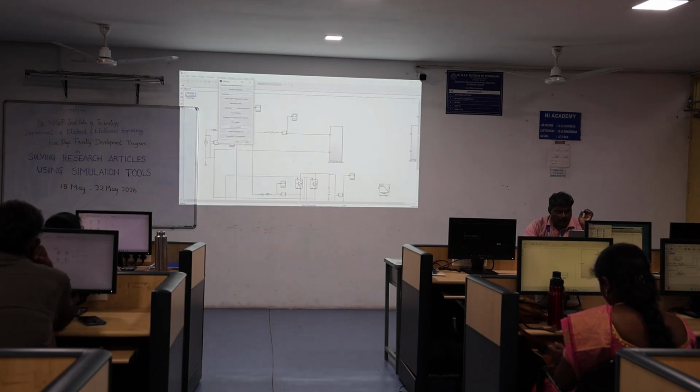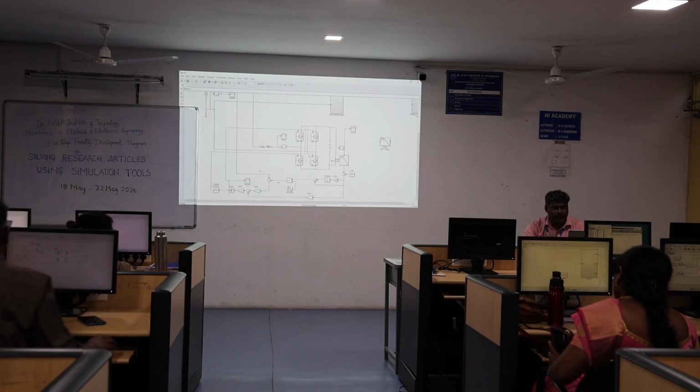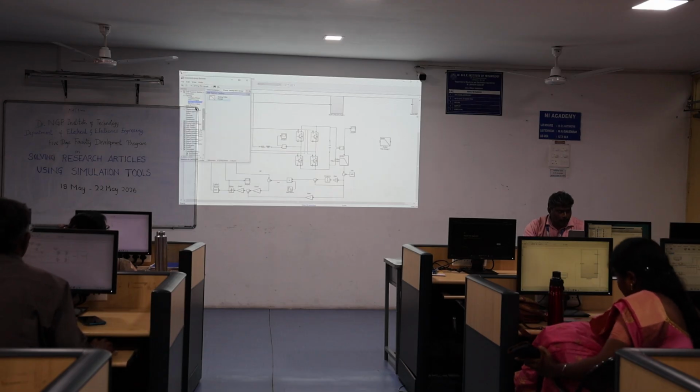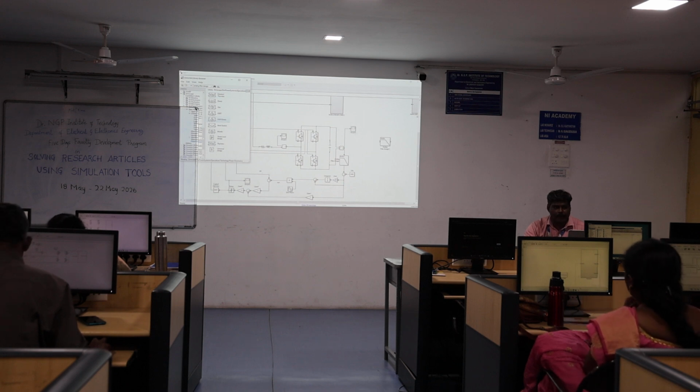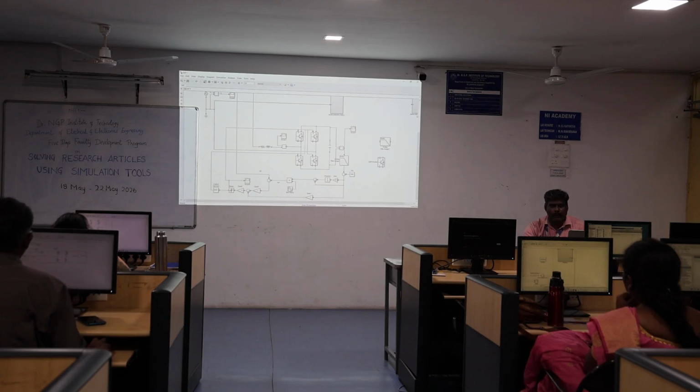I will tell you where the components are available in the Simulink library browser. So all of you take down the component. Okay, so now I want to construct this inverter switch. First go to Power Electronics. Take the IGBT. Then Ctrl R to rotate. You can simply copy, then you can connect them to form the inverter like this. Right? You just construct the inverter.